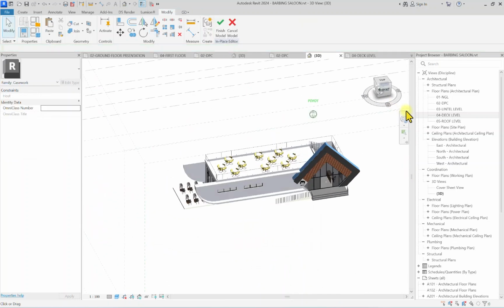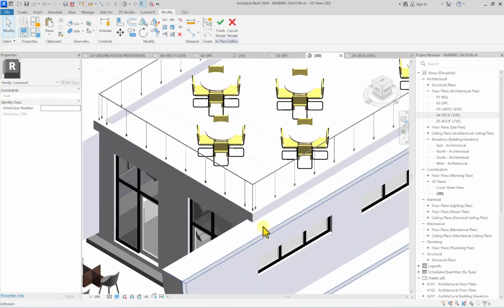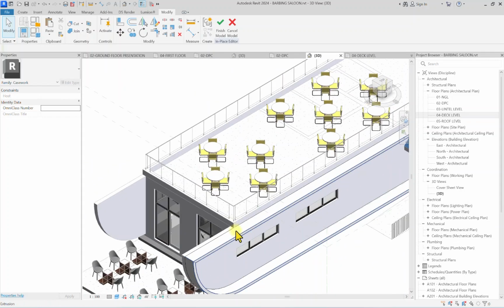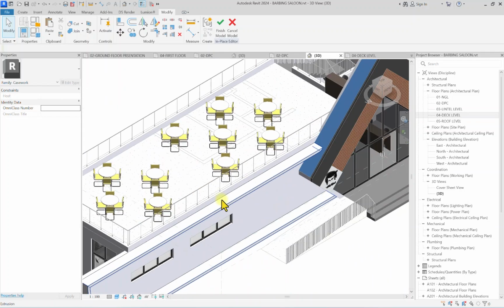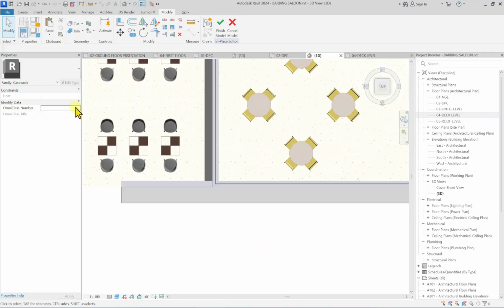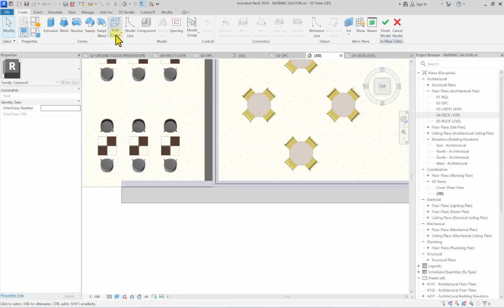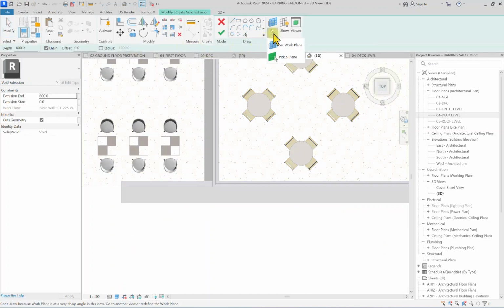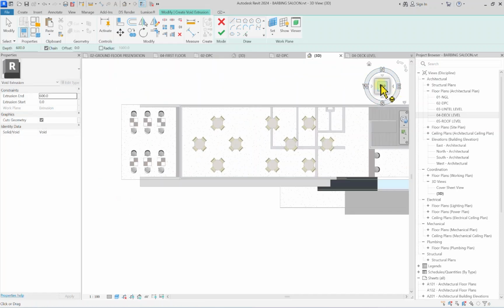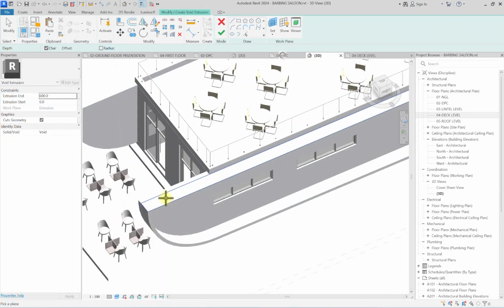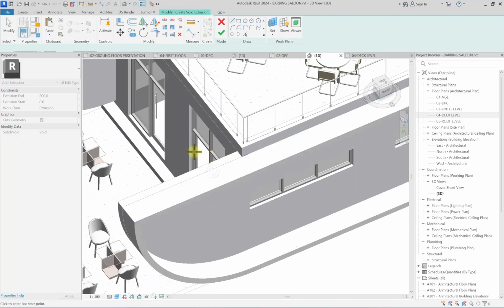So I'm going to do some things because in as much as there are panels here, I want air to be flowing in and out of this stuff. So I'm going to use void extrusion to cut open this top part. So I'm going to rotate this to this top. I'm going to click on Create. I'm going to click on this drop down, Void Forms, Void Extrusion. Then I'm going to click on Set, Pick Plane, and I'm just going to pick the top of this.